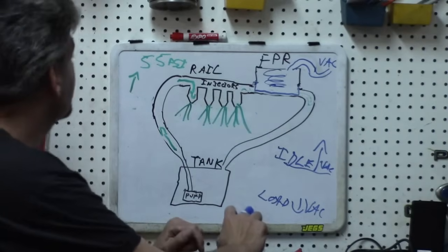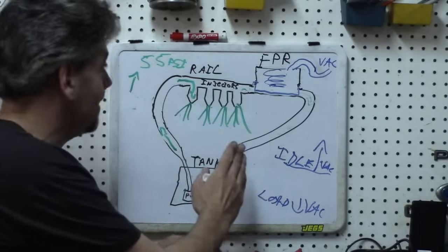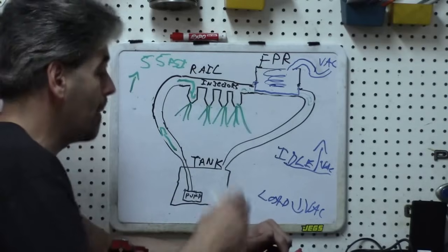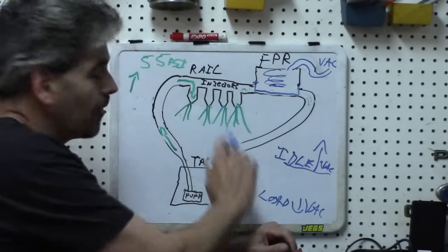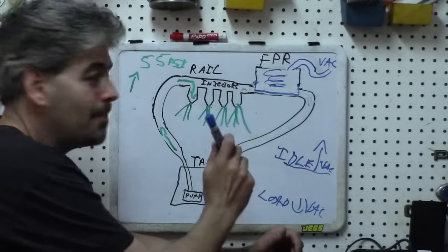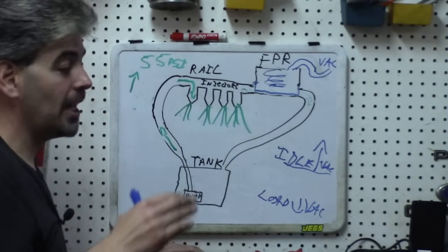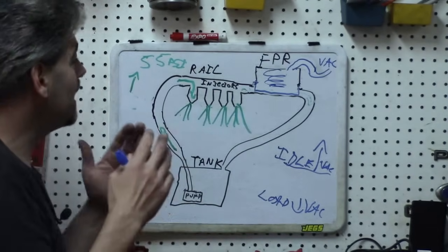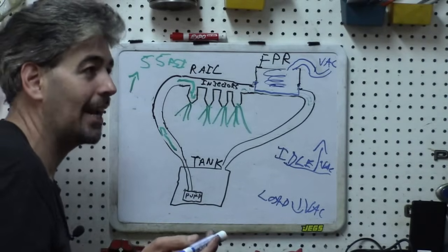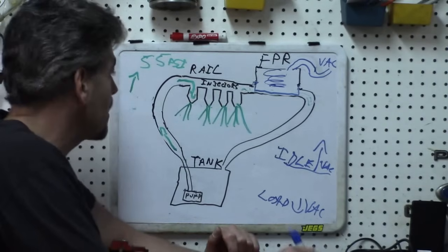Let's go over some of the common problems that may indicate a fuel pressure regulator, and how you would go about testing them to make sure that you don't replace the fuel regulator if it is not the problem. So one common problem that would maybe key you towards the fuel pressure regulator would be if the engine is running rich. There are a couple of codes that would be identified with this. You might even have a check engine light. I guess it would be a P0172, maybe also a P0173, I believe.